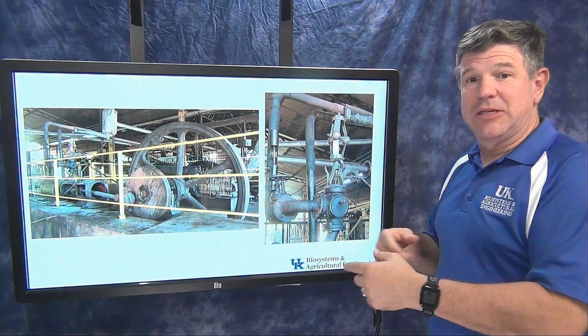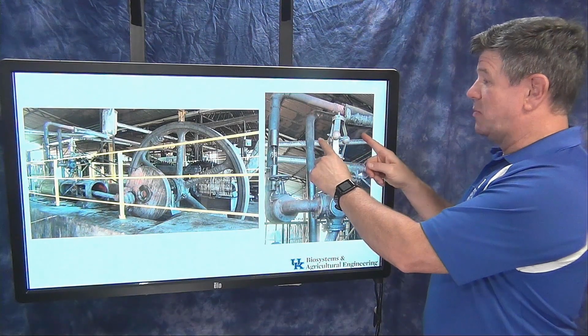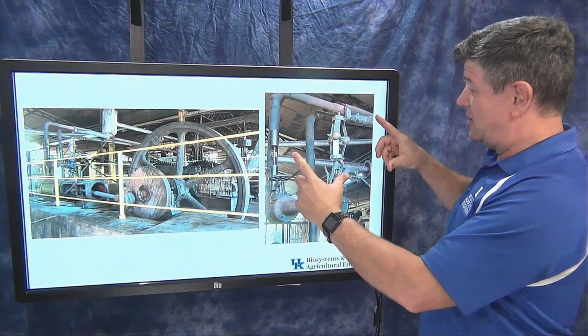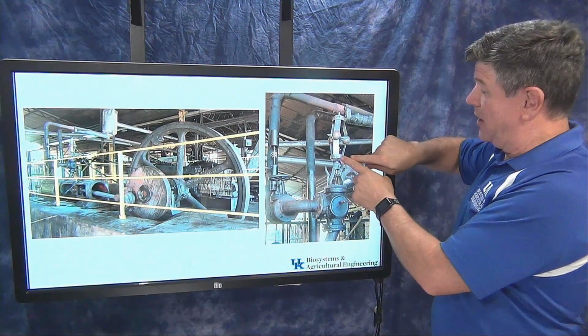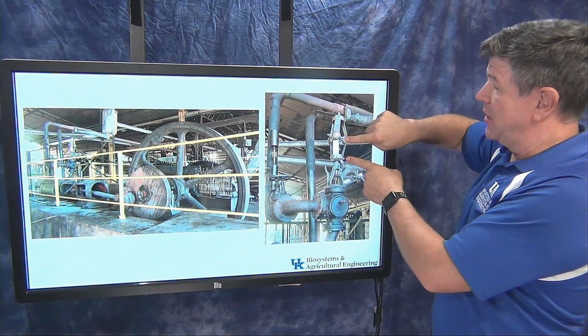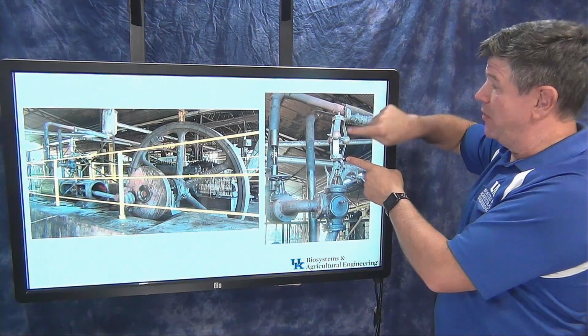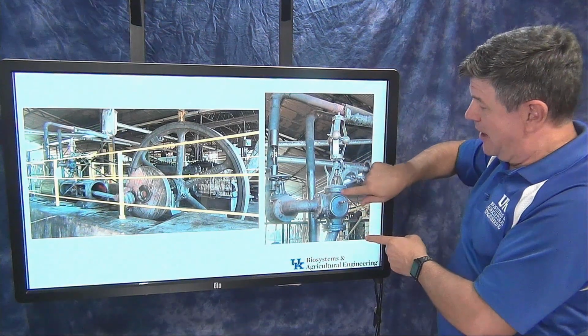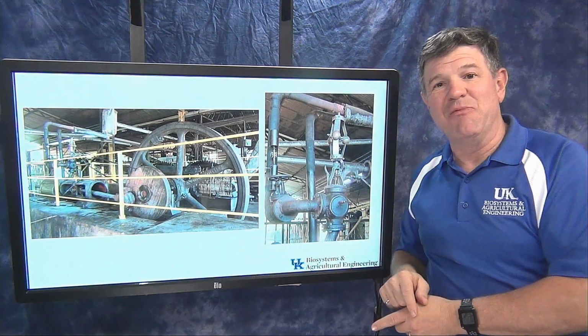So the faster that steam engine spins, the more these balls go out. So they're flying out, they go out. And again, that scissor mechanism, and on this particular mechanism, the bottom is fixed because that's where the gear is, but the top is going to move up and down. So the top of this thing will move up and down. The shaft that goes through there goes down into here, and right in this area is a steam valve.